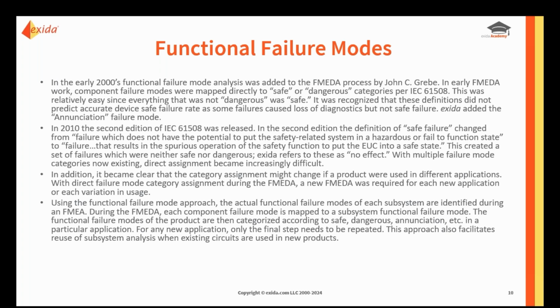In many cases, when you do an FMEDA, you'll discover that the product doesn't meet its intended safety integrity level, and the designer will make changes to the product. And it's quite involved to go back through all the components and figure out, this used to be diagnosed at a low effectiveness, and now it's being diagnosed at a medium effectiveness.